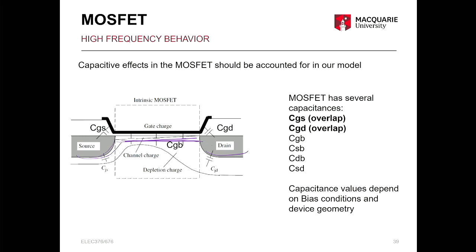So how does it impact its frequency performance? Yeah, the gain goes down much earlier in frequency. So if the BJT can operate up to 200 megahertz, the MOSFETs can operate only much below that. It will not go up to 200 megahertz.